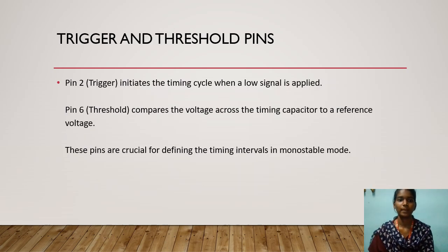Trigger and threshold pins. Pin 2 trigger initiates the time cycle when a low signal is applied. Pin 6 threshold compares the voltage across the timing capacitor to a reference voltage. These pins are crucial for defining the time intervals in monostable mode.